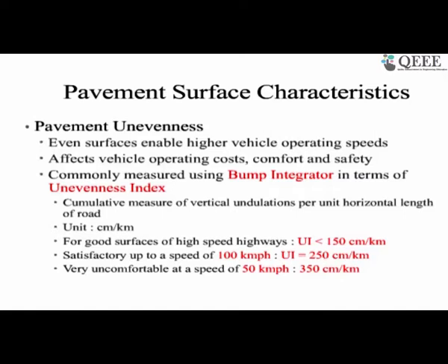Okay, so now I'll move on to the next slide, and before I move there, there are two questions which I'll be addressing. One is, which is more complicated, skid or slip? If you look into the situation when it is happening, skid is happening when you are applying brake and the vehicle you are trying to stop will take a longer distance. Whereas slip is happening when you are trying to accelerate, or when the vehicle is starting from a standing or stop position. So in this case, again you are trying to accelerate and the wheels start slipping.